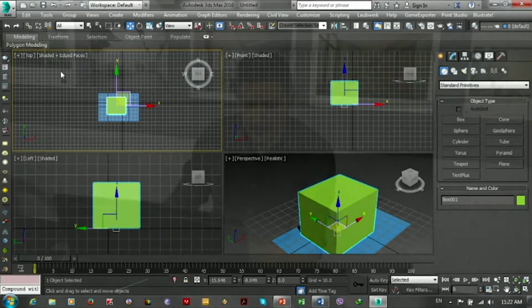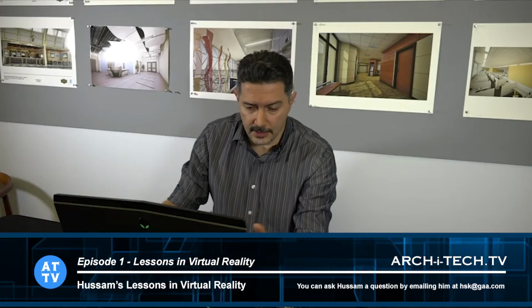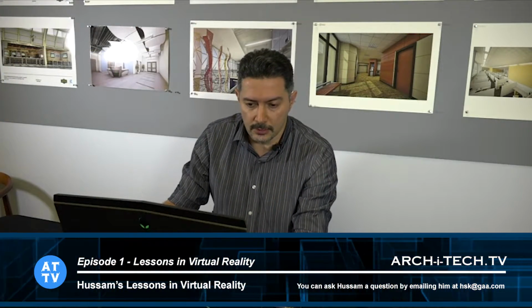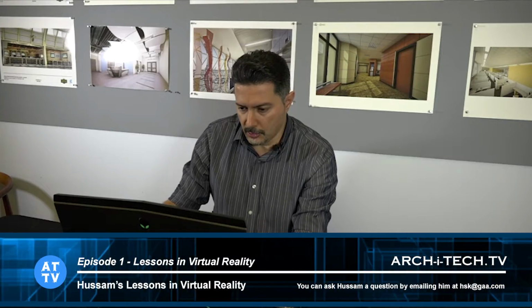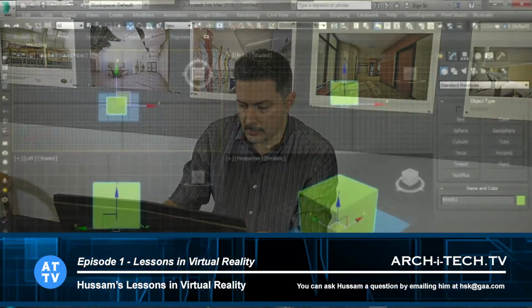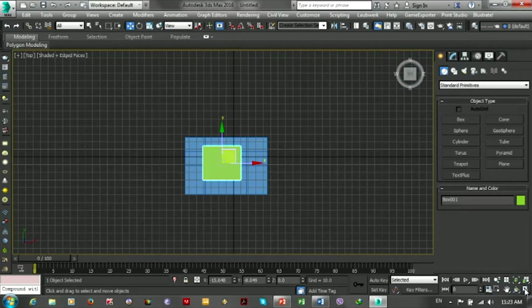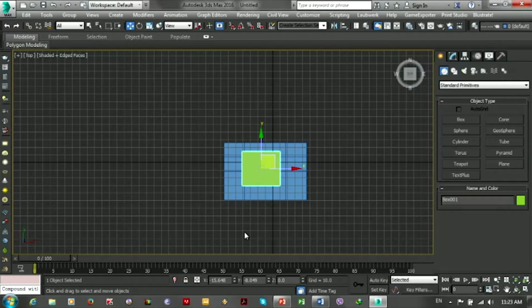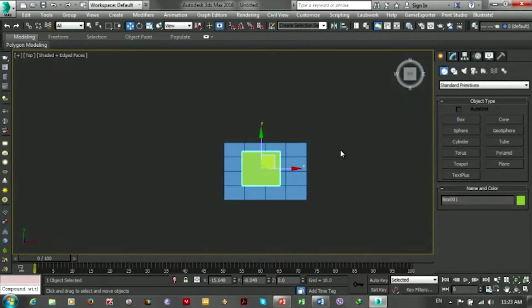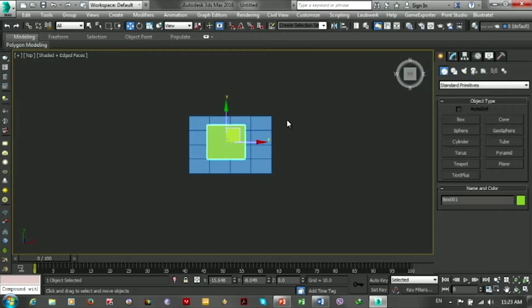And some of you maybe said, okay, how am I going to work with these small windows here? So you go all the way to the lower right corner and press toggle viewport, which maximizes and minimizes the viewport itself, and that will give you more space. And if the grid itself bothers you here, you can hide it by pressing the G button on the keyboard. And that will, as you can see, hide and unhide the grid as well.